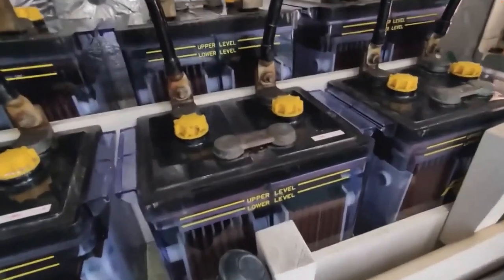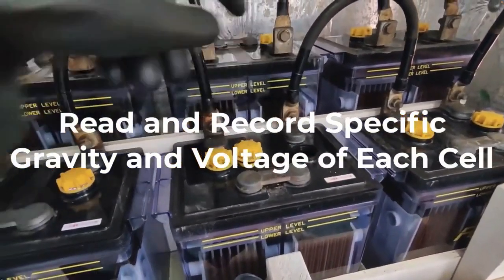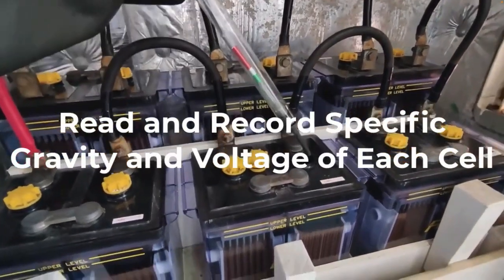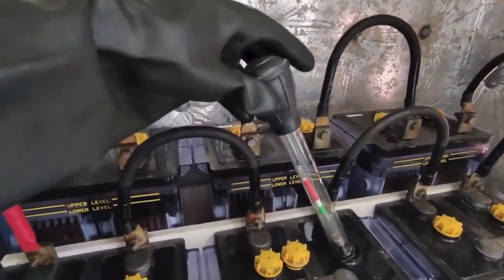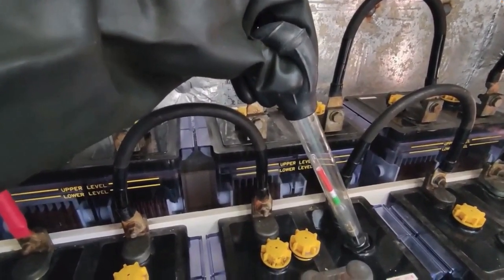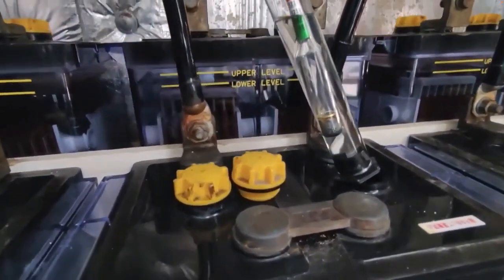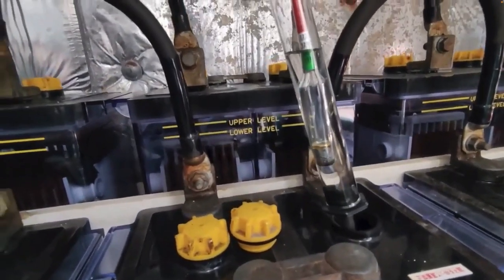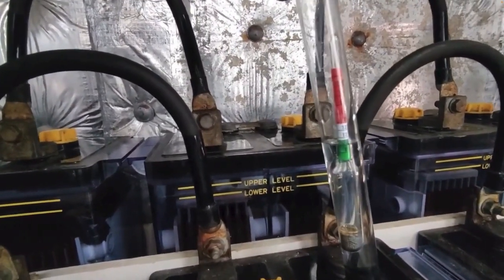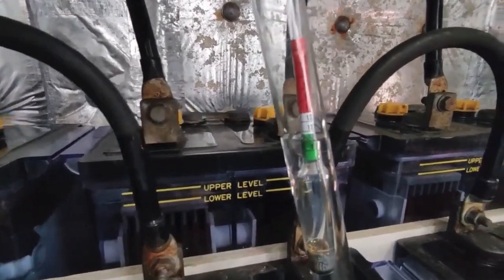Therefore, the IEEE standard 450, which is the recommended practice for maintenance, testing, and replacement of vented lead-acid batteries for stationary application, states that the battery should be equalized and returned to float for 72 hours prior to conducting a battery discharge test.